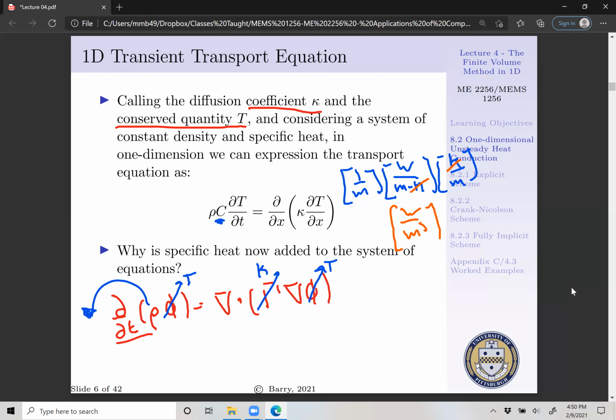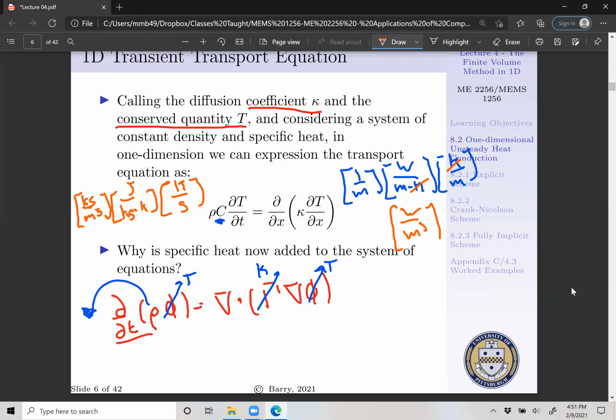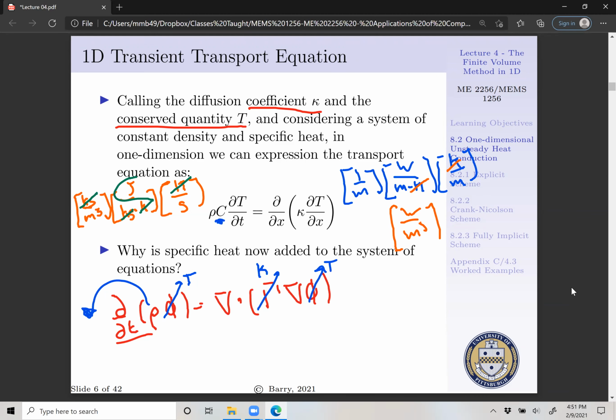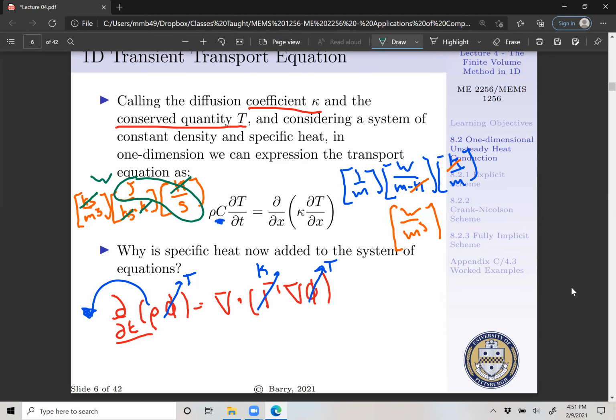Awesome. Now, what we'd have on our left-hand side is our density, taken as kilograms per cubic meter. Our specific heat is taken as kilojoule per kg K, or we could express this as simply joule per kg K. The kilo is not important. And then in our numerator, we have units of temperature. In our denominator, we have units of seconds. So if we cancel out these units, we see mass cancels out, temperature cancels out, a joule per second becomes a watt, so we'd have watts per cubic meter.